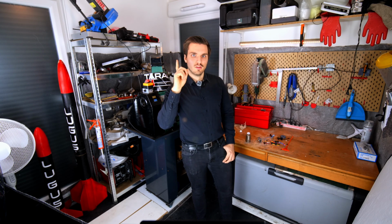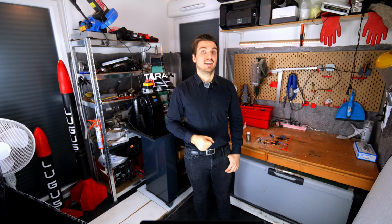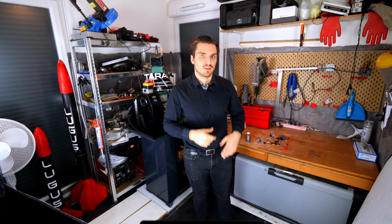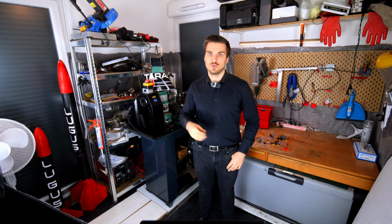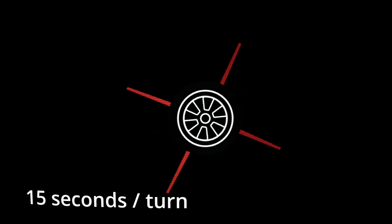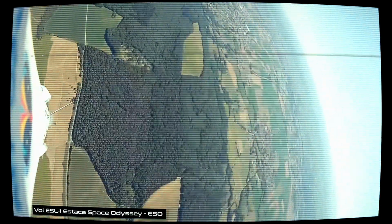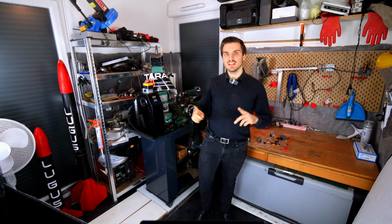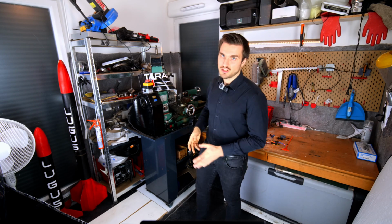Finally, there's one remaining scenario: that the rocket has no roll at all. Because yes, it happens. If you're not sensitive enough, the rocket will not rotate, at least not enough to trigger the stabilization. So we have made the choice to control the roll, not to cancel it. We plan to turn on ourselves at the desired speed, and in one direction. It will be a reasonable speed of 1 turn in 15 seconds, which is really slow. But this would also have allowed us to validate the experiment with the views of the cameras, which will slowly rotate on themselves. And it's still not over, because there is a big part we haven't talked about yet. But honestly, for many projects you can stop here.